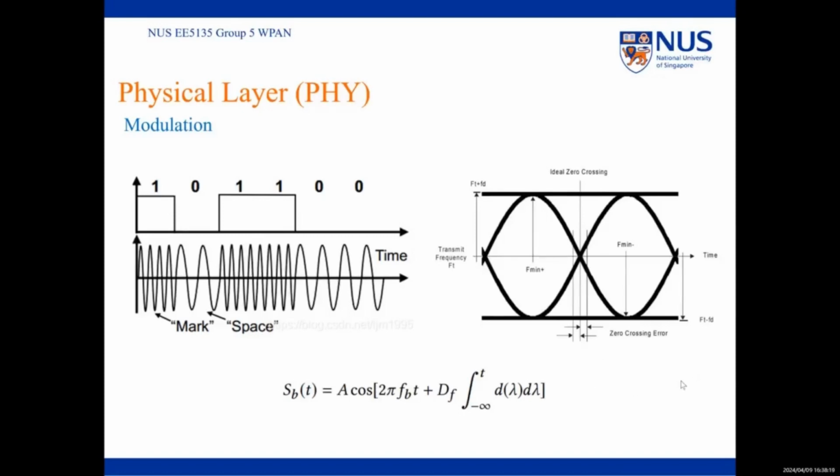The modulated signal undergoes further filtering using a Gaussian response curve, limiting the extent of the sidebands around the main carrier frequency. This ensures Bluetooth modulation achieves a bandwidth of 1 MHz, with strict filter requirements to prevent interference on adjacent channels. To maintain proper operation, the BT level is set to 0.5 and the modulation index must fall within the range of 0.28 and 0.35.